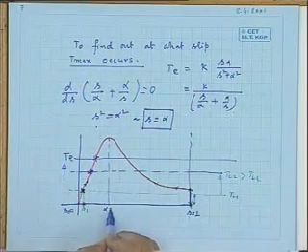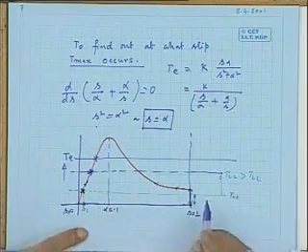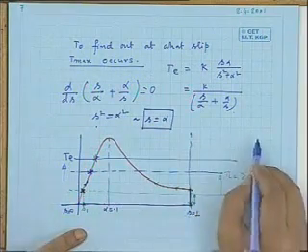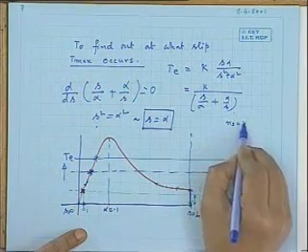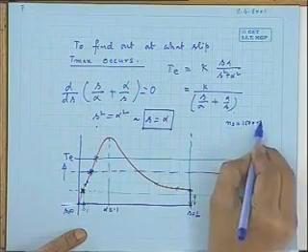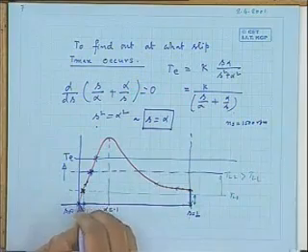About, I told you, about 10%. This value of slip, a typical value of slip, is generally 0.1. So suppose it is a four-pole machine, let us take an example. Suppose the synchronous speed is 1500 RPM.